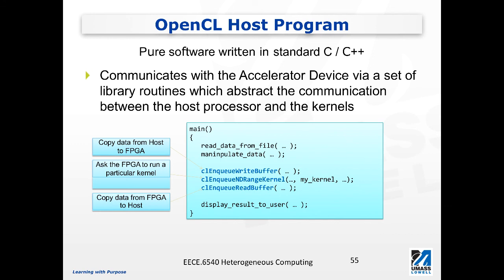The program on the OpenCL host is really a pure C or C++ software program. It's a serial program. There's really no parallelism on the host side software. The communication between the accelerator device and the host is handled by using these enqueue buffer operations.